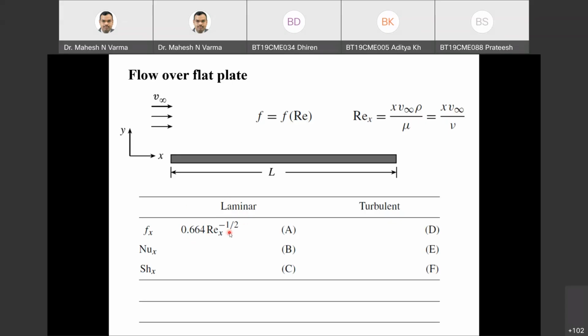Okay, then this is for turbulent flow only, this is for laminar flow only, and this is for turbulent flow, and this is purely experimental. You can say it is experimental model fitting, a polynomial fitting equation in the form of f as a function of Reynolds number. So the observation is wall flux and observed Reynolds number; try to fit these values to get the friction factor, and this is a purely experimentally derived equation.